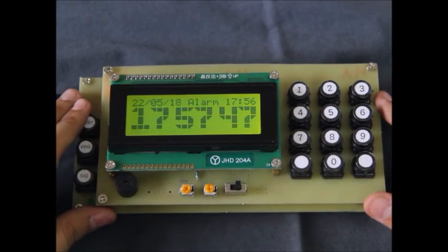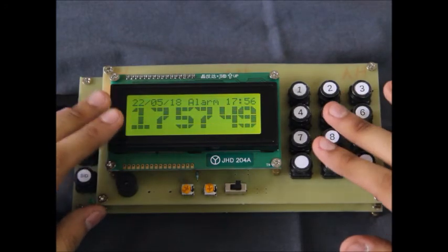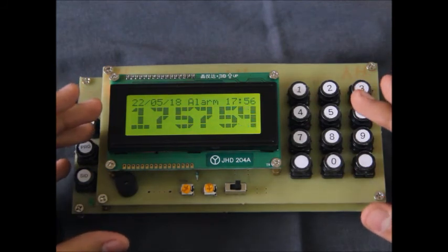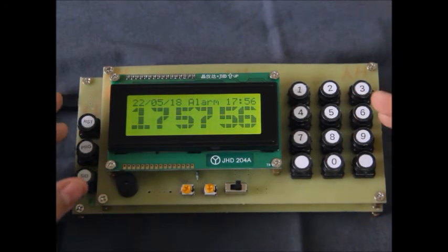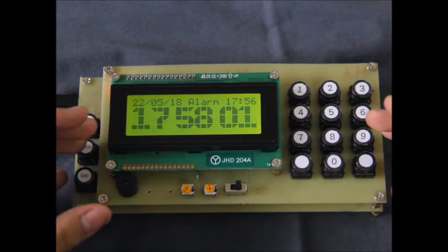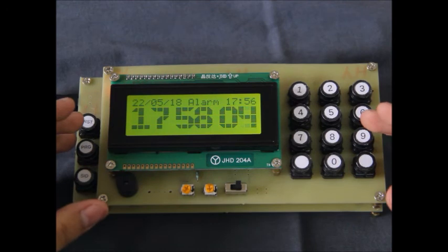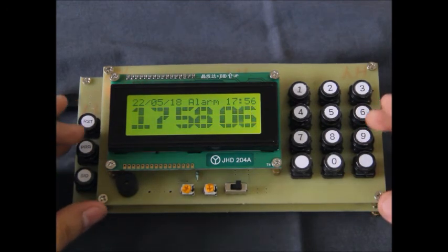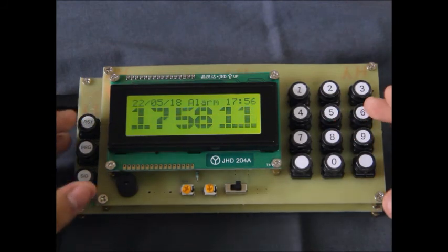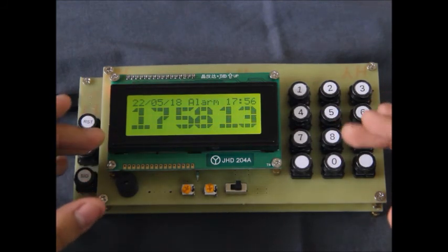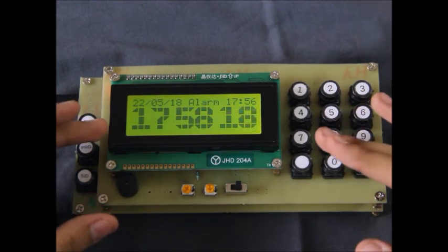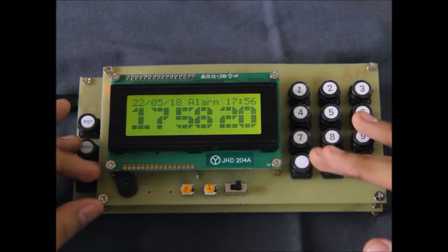In this project, I'm using big font on the LCD to make it look prettier. On a character LCD, you can generate characters as well as some custom shapes by storing them into the memory of the LCD. So that's what I've done with this project. I've stored some special shapes and I've printed them and made digits out of them, which are big digits. They are using 3 rows and 3 columns basically, and this effect is generated by that.